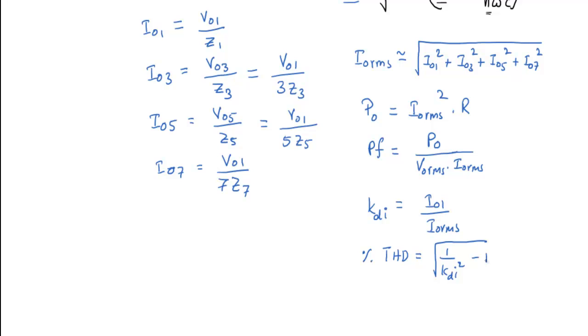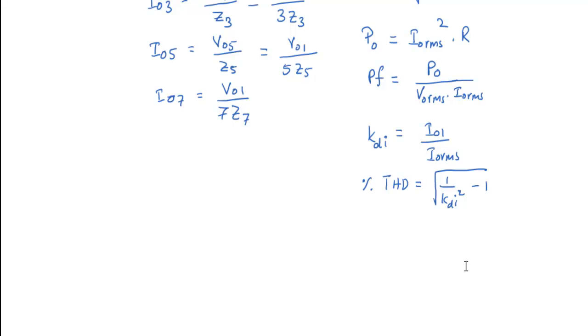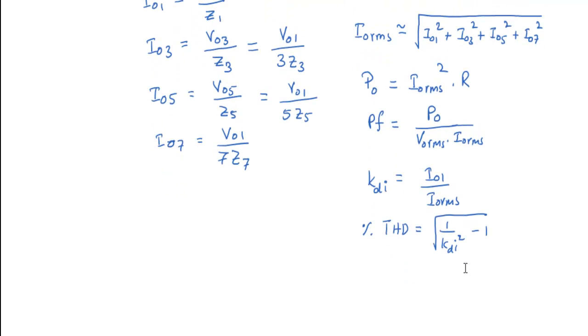Okay, so finally using the power balance equation, power supplied by the source, that's VDC IDC, equals power consumed by the load, that's P0, assuming everything is lossless. Using that power balance equation, we can calculate average source current, which is power consumed by the load divided by source voltage VDC.